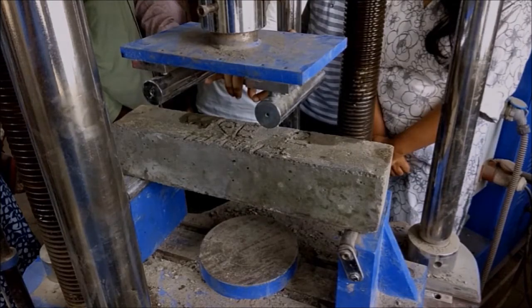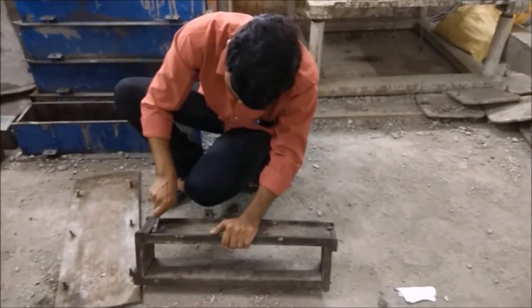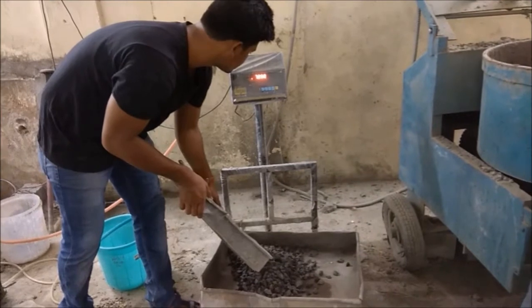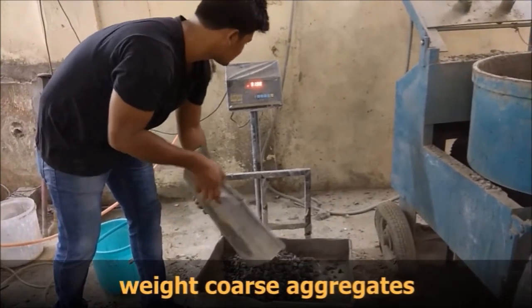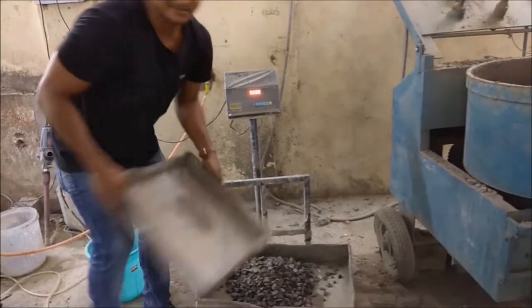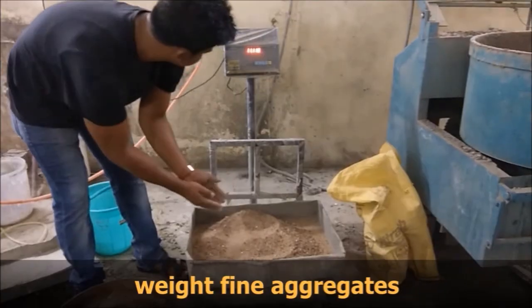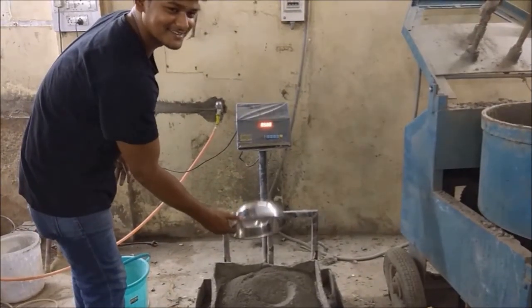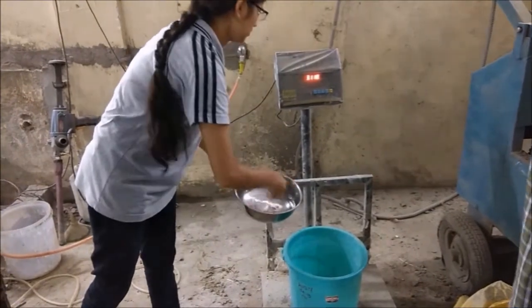Now first we have to tighten the beam mould so that there is no bleeding. Then we take coarse aggregates with the weighed amount that we calculated in the mix design. After taking the coarse aggregate, we weigh the fine aggregates with the amount that we calculated. Then we weigh the cement, and then we weigh the water. Whatever water is required, we just weigh it and take it.